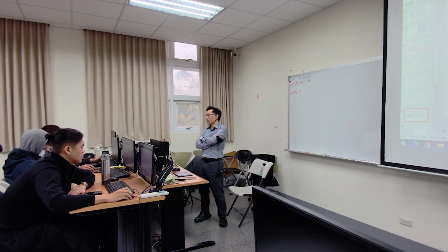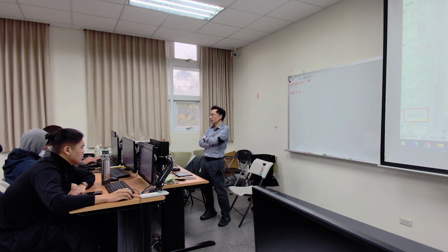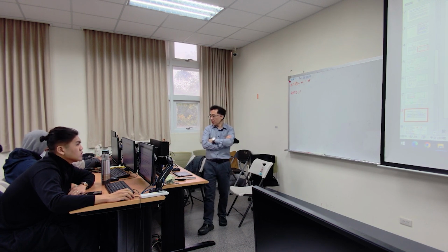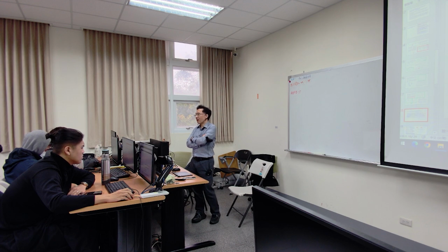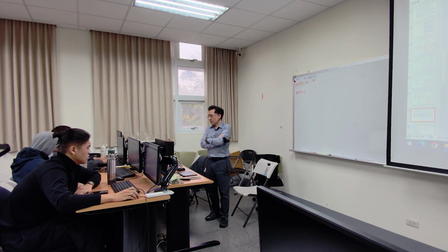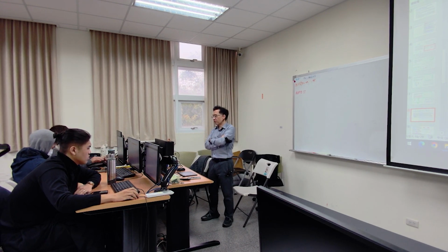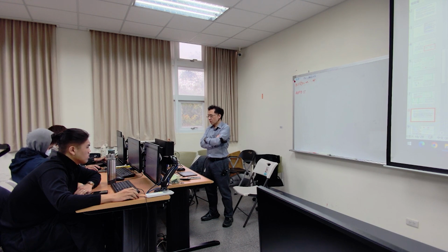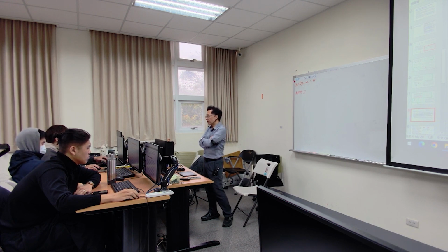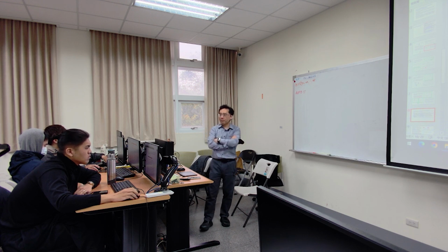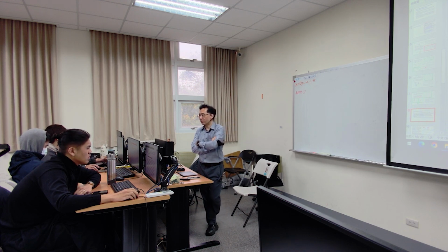Even with the same robot, if you choose a different coordinate frame, then the answer is not unique. The frame is not unique, so different engineers will deliver different but equally correct results. So you need the manufacturer to provide the DH parameters to you.